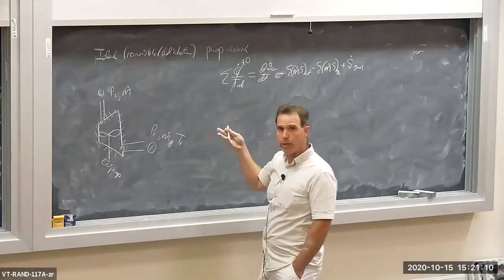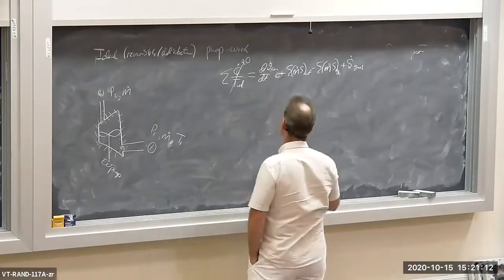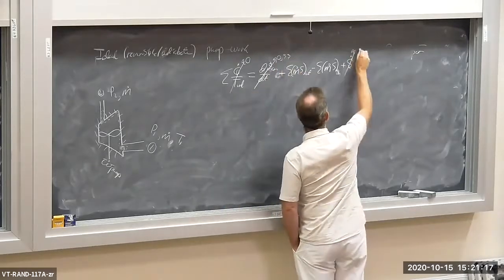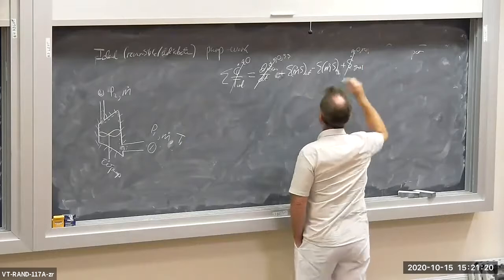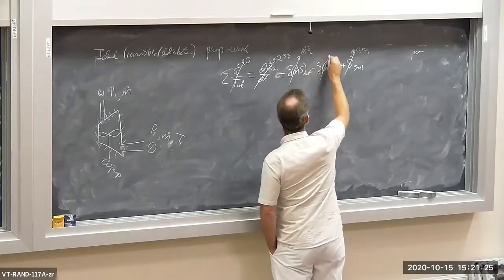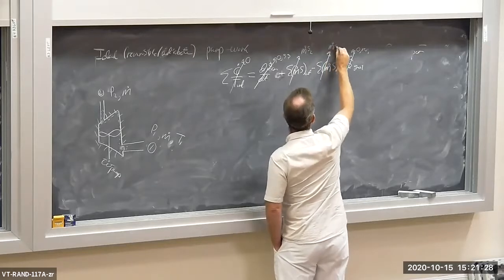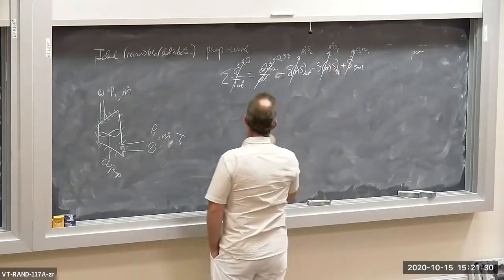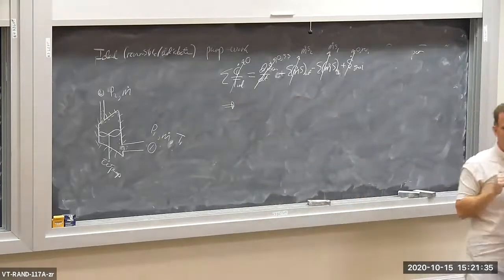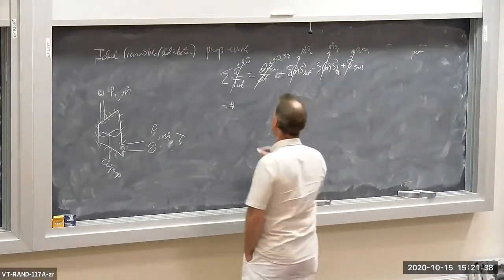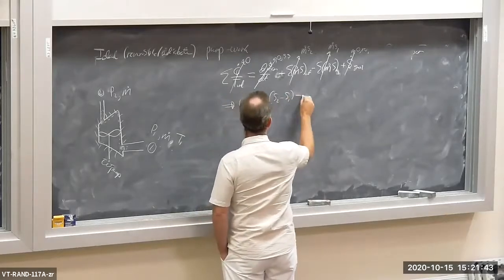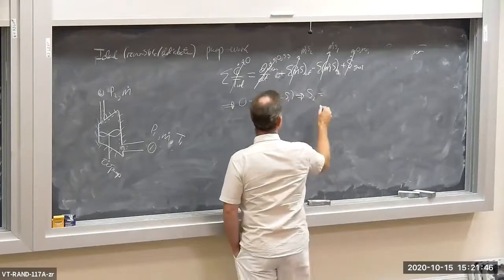I think we're going to assume steady state here, and every single problem we've done has been a steady state problem. So this is going to go reversible. Single inlet, single outlet. So we got m dot S2, m dot S1. And so I get the mass flow rates are the same going in and out if you apply the mass balance. So I get 0 equals m dot S2 minus S1, or S2 equals S1.